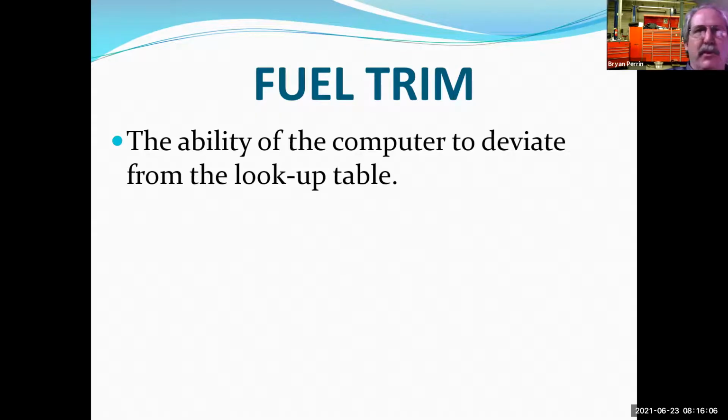Because with all the simple low-hanging fruit, you don't even have a ladder or a hook. I mean, you're like, what the heck is going on here? These cars don't fail this way. And especially at idle, because if it's a fuel pump problem, we're going to see it off idle at high demand, not at idle. So then you're really wondering, what the heck is going on here?